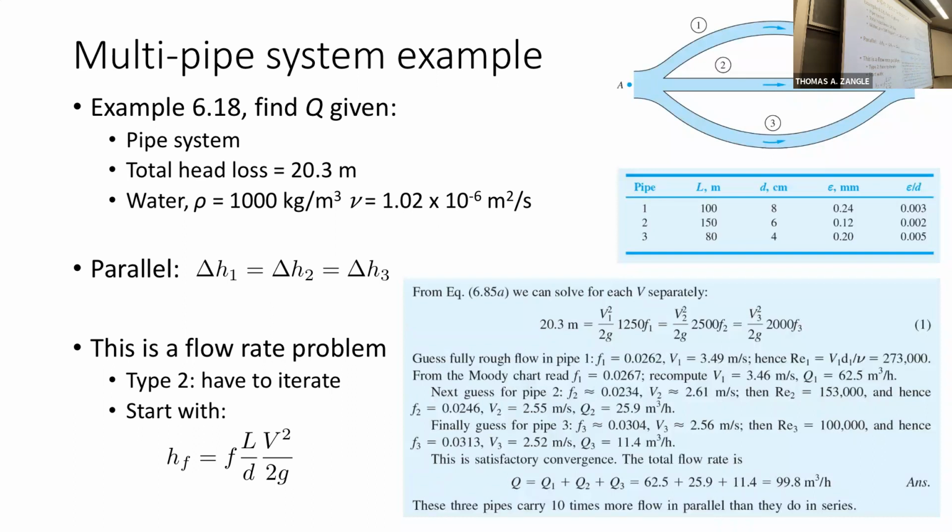If they're all the same diameter, they're all going to have the same flow. But the friction factor, the head loss is the same. Oh, sorry. Yeah, no, you're right. If they're all the same diameter and length, then the flow rate in all of them is going to be the same. But yeah, they are different lengths in this problem. Sorry about that. So you could use what you know from the first problem to help you in the second one.